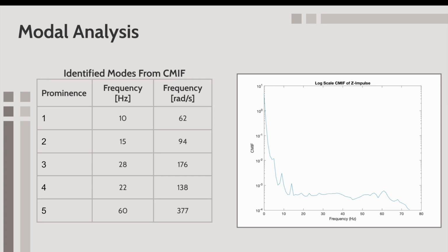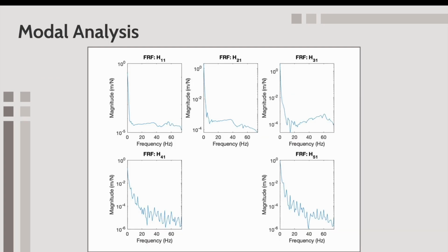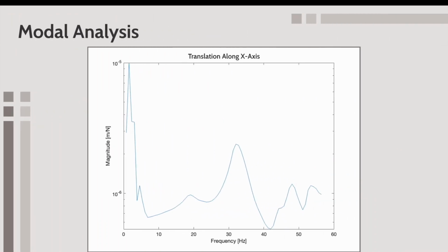The final method of modal analysis used was transfer function fitting via MATLAB's System Identification Toolbox. Initially, the analysis was attempted using the original data, but it then became evident that the resolution at the low frequency modes was not sufficient to obtain meaningful results. This is due to an impulse hammer being used as the excitation method as opposed to a shaker, which performs better at low frequency ranges. Instead, previously collected data of the printer's response to sine sweep excitation in the x direction was provided and analyzed.